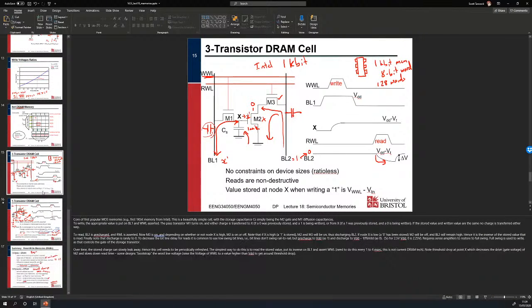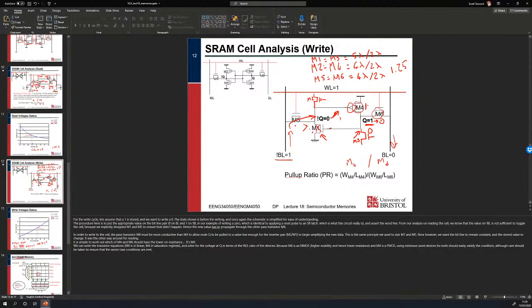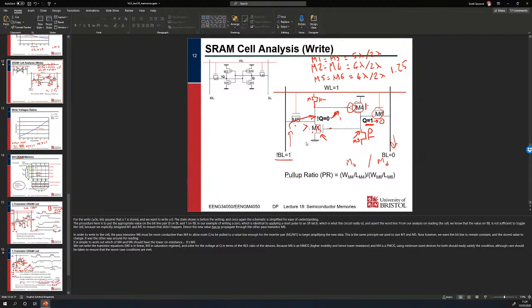However, when idle, this cell consumes very little power at all. There's only the slight amount of leakage through the transistors, and because they're high VT transistors, they're designed to have low leakage. That leakage isn't particularly high, right? So you end up with a cell that doesn't really consume much power when it's idle. Although obviously there are more transistors, but yeah, in general it doesn't consume much power.